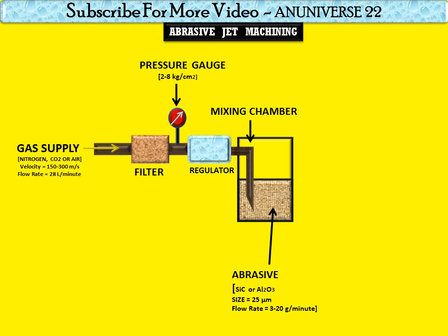And commercial grade powders are not suitable because their sizes are not well defined, and they may contain silica dust which can be a health hazard. And it is not practical to reuse the abrasive powder because the contamination and worn grit will cause a decline of the machining rate.